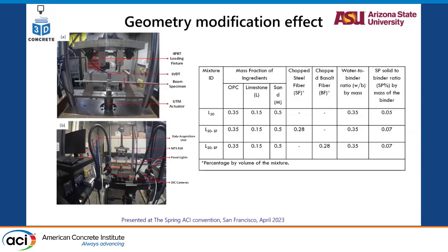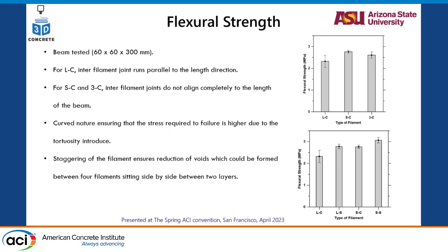and the tensile strength that it could sustain was 3 GPa, while the basalt fiber was about 10 times smaller in diameter, about 0.04 mm, while the length was 15 mm itself, but the strength again a 10-fold decrease at 0.3 GPa. That will come into consideration later, because with 0.3 and 3 being the strengths, there is something that we saw that is quite fun to see. So from the slabs that I showed before, we cut out 60 by 60 by 300 mm